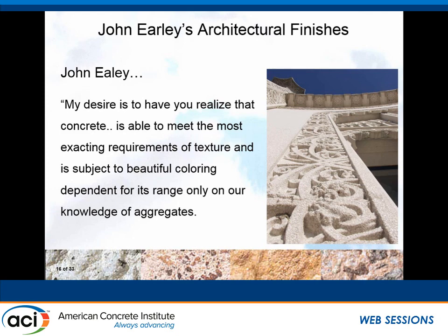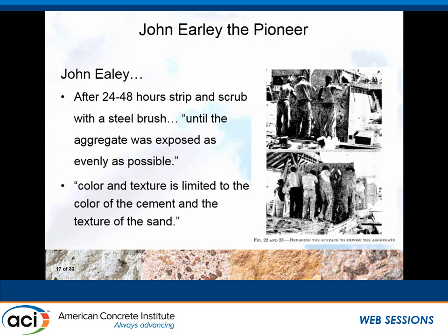His knowledge of aggregates was terrific. We talked about it, Bob, you talked about it a little bit earlier. He changed the grading on his aggregates just a tad to coarsen up his sand, and he got that strength he was looking for. He was able to extract that water that he didn't want in his mix. And he was able to use that to ensure that when he stripped his forms in 24 hours, which they did at the Baha'i Temple, they would be able to get after it with those wire brushes.